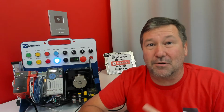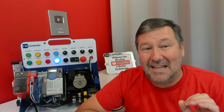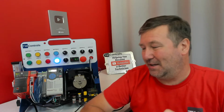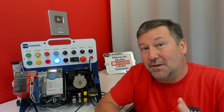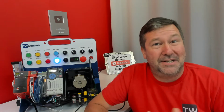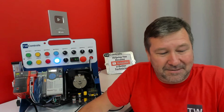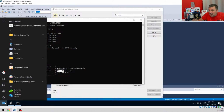Now, on industrial networks, we almost never have a DHCP server. And even then, you're probably not going to be on the right network if you hit one. So we're going to walk through a couple of those. But so now we need to know, how is our computer actually configured? And to do that, we need to go to our Windows network configuration. Now, there is a dozen different ways to do it, but this way actually has worked, I think, since maybe Windows XP. We're going to go to our Start menu, and then you're going to fully type it.